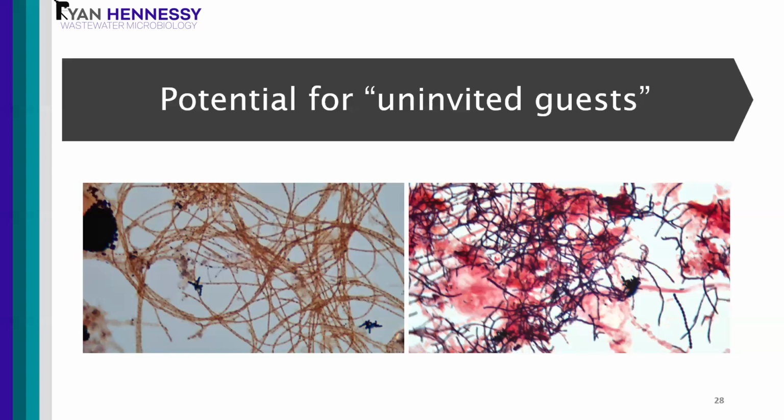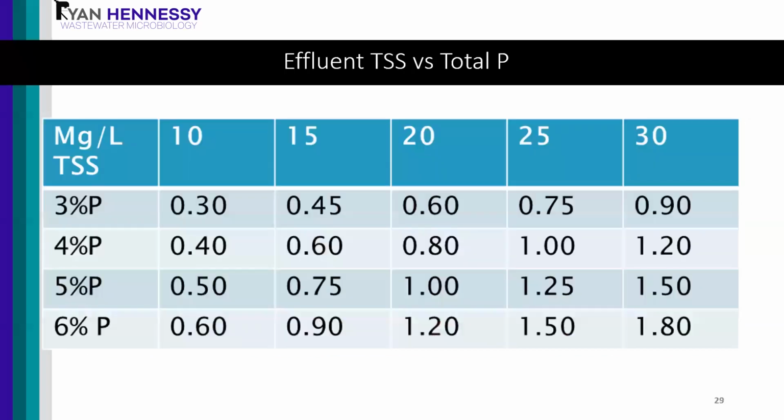So it's always a case by case thing, but there are some instances where, perhaps at certain times of the year, if it's a small plant and the Microthrix likes the cold weather, from an operational standpoint maybe you would use chemical phosphorus removal in the winter versus trying to get BioP and then seeing higher Microthrix. But there's no right or wrong thing. There are a lot of different things, and you have to make sure you're optimizing and doing what's best for your individual circumstance.